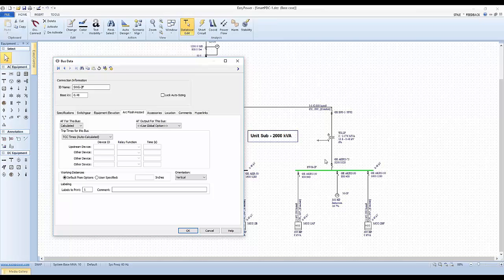And the reason for that, if you look at the IEEE results, is they discovered that once the plasma ball has been initiated, whether we initiate an arcing fault on the bus side or on the upstream side of this breaker, once that plasma ball has been established, it can propagate the source of the arc anywhere within that ball.